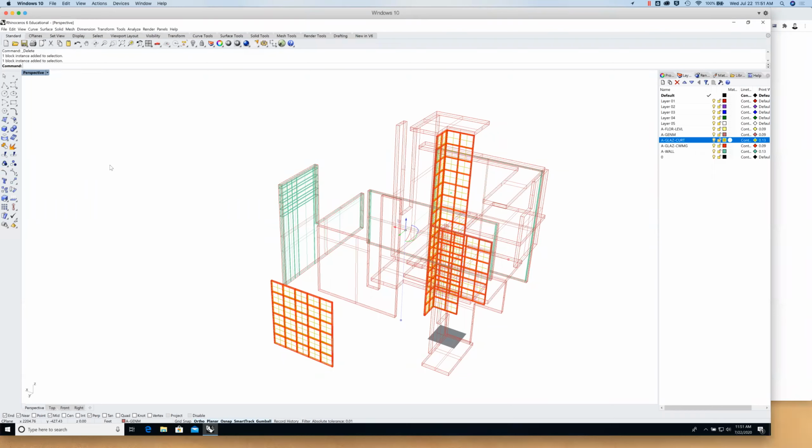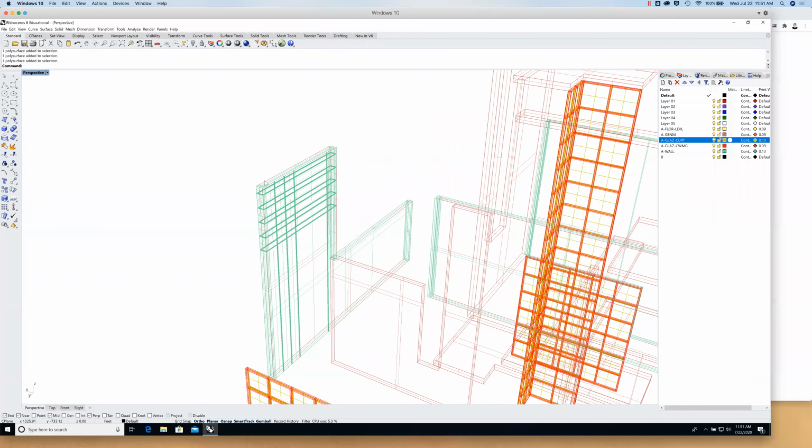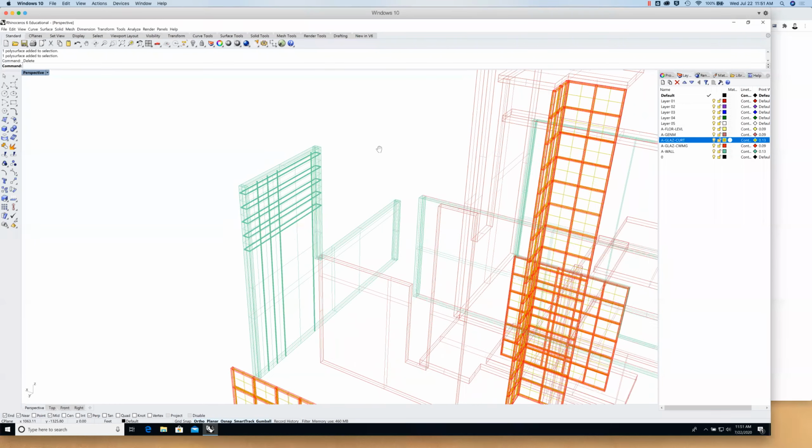And I'm going to just go ahead and type in explode in order to explode that block back into, you know, there's an extrusion, there's an extrusion, there's its own extrusion, right? Now, this extrusion is redundant. I'm just going to go ahead and delete it. So that way we get to see just the stuff here, the reveals and things like that we made, okay?